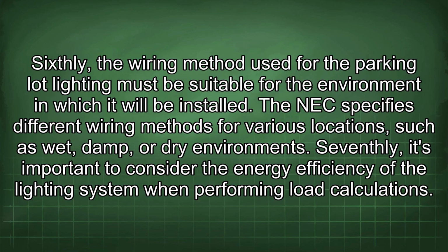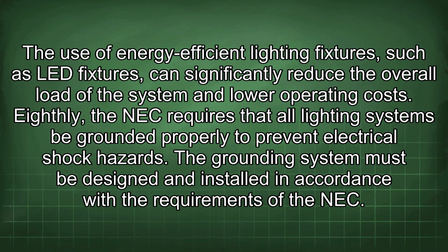Seventhly, it's important to consider the energy efficiency of the lighting system when performing load calculations. The use of energy-efficient lighting fixtures, such as LED fixtures, can significantly reduce the overall load of the system and lower operating costs. Eighthly, the NEC requires that all lighting systems be grounded properly to prevent electrical shock hazards. The grounding system must be designed and installed in accordance with the requirements of the NEC.